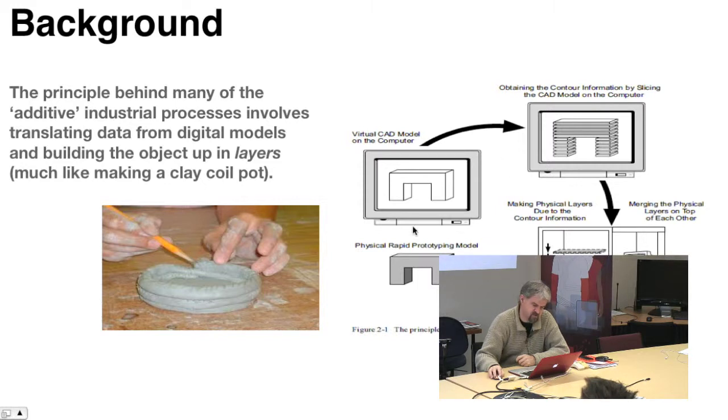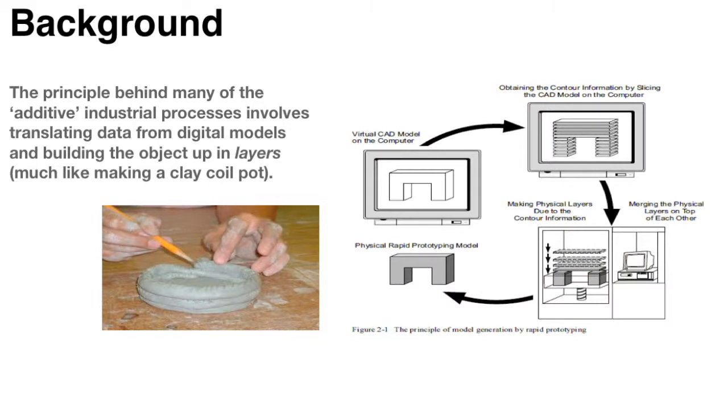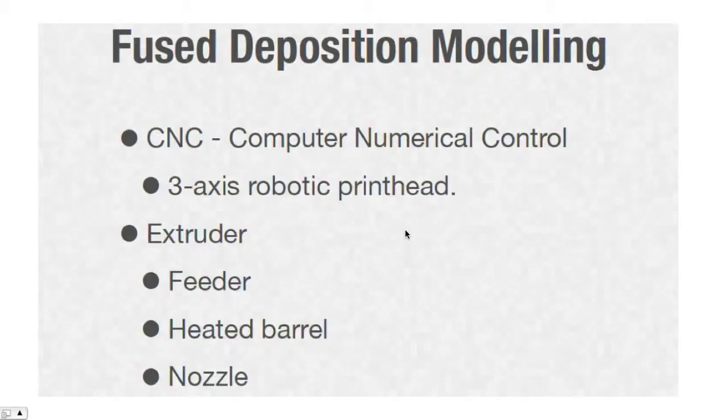The basic process is you start with a CAD model, and from the CAD model you create slices, and you produce an STL model, which is a template model, and then you send that to the 3D printer. The printer then uses an additive process to deposit material on those slices, and it makes the final prototype at the end. And a fourth method is a fused deposition modeling method.